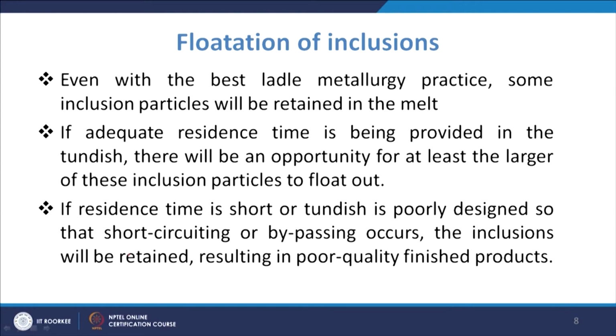As we discussed, we try to do the treatment in the ladle, so that most of the inclusions we are trying to remove from there itself. But still, as we had seen, some of the inclusions are likely to still come into the Tundish, and we have to try to remove these inclusions.